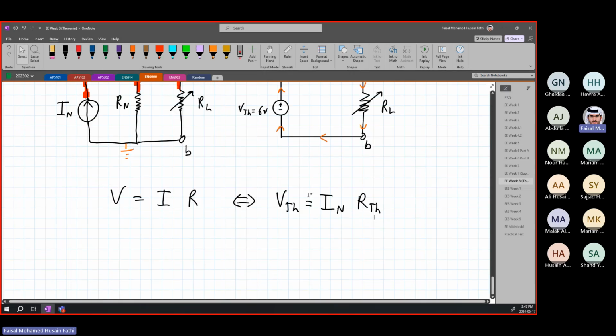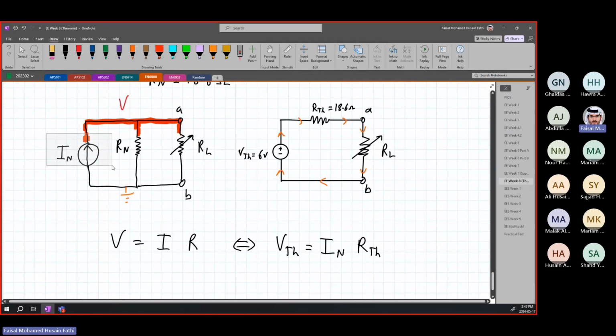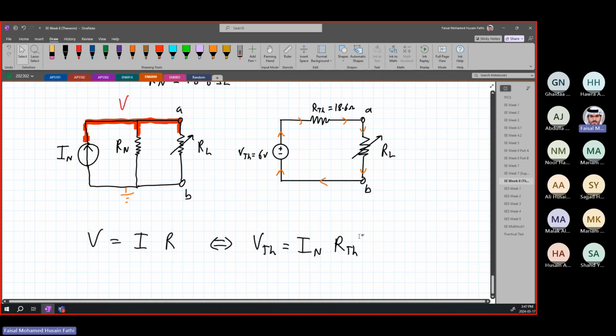So this is another thing. The current source that is being used over here is going to be equivalent to the voltage drop due to the R Thevenin resistor. This is an important relation you can use, because this way, if you solve using the Thevenin method, you can find your equivalent I Norton instantly.